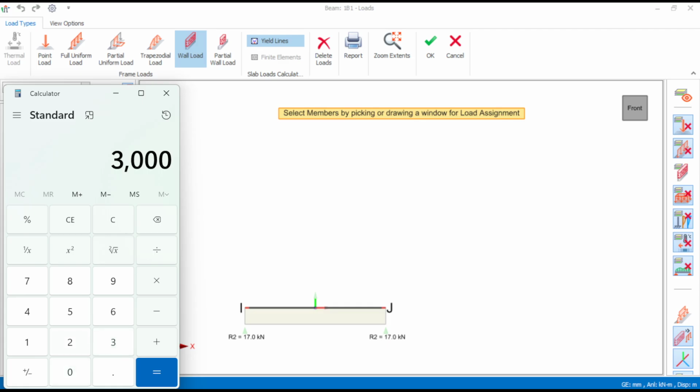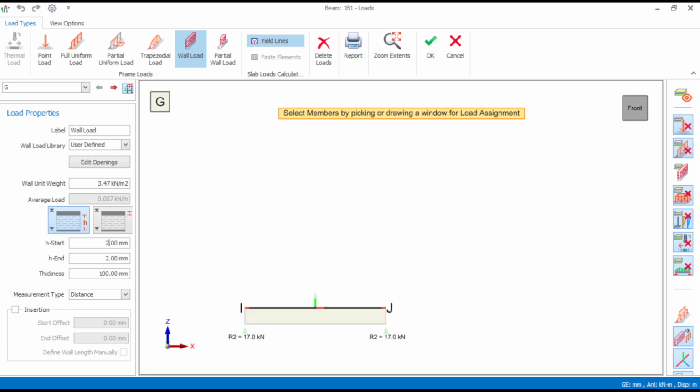Remember I told you that the beam is a 450 beam, but for a 450 beam, 150 is going to flush with the slab, while 300 is going to drop. So it will now be 3,000 minus 300. That's 2,700. So for this place, we are going to put a 2,700 height for the partition. Now in Nigeria, the thickness of my block is actually 225. Then plus plastering and stuff, then we can just say this one is 230.